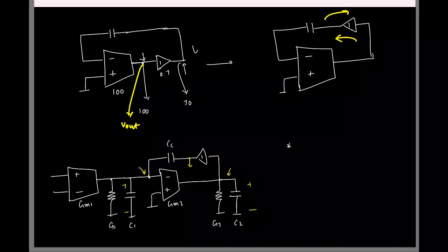So you have only two poles, and that's expected. The two poles will be at approximately the same location as before. And now we expect that we don't have a zero. We can also quickly verify by shorting the caps. If I short capacitor C1, this voltage is 0, so this will also go to 0. Fine. If I short C2, it's trivial, the output is 0. So let's see what will happen if I short CC.